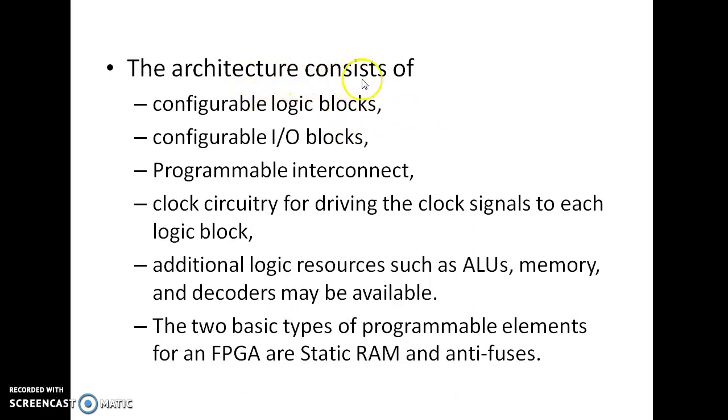So the architecture consists of logic blocks, or configurable logic blocks. We say configurable because, according to the logic function, you can connect or disconnect the internal connections of logic blocks. It is nothing but programmability by using fuses, as we have discussed in PALs and PLAs.